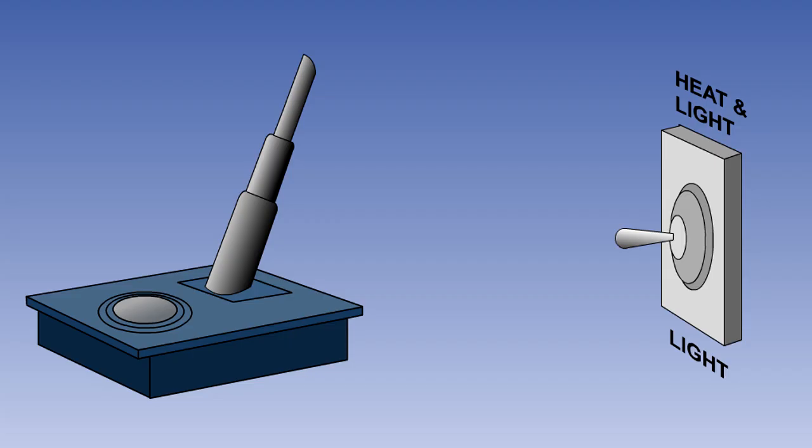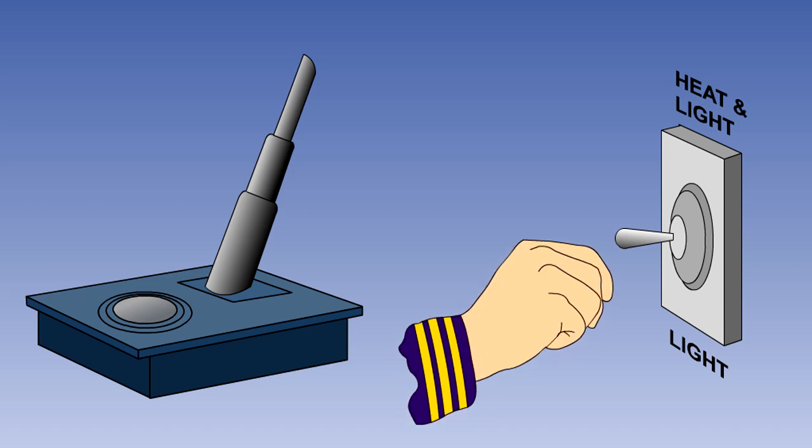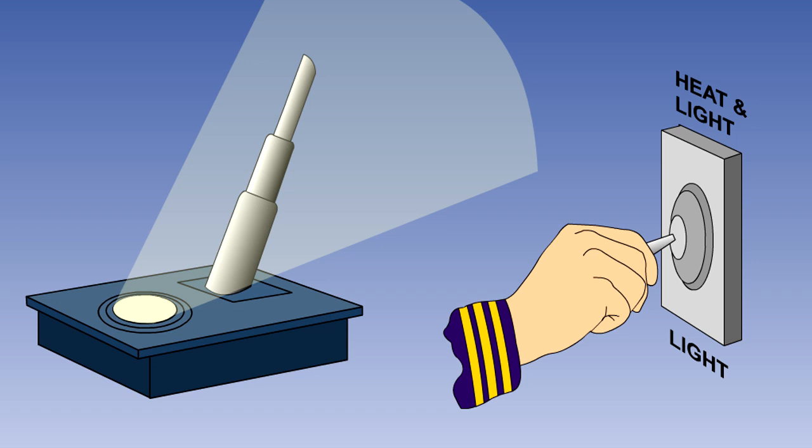To assist the pilot, some aircraft have a device known as the Teddington ice detector. This detector consists of an aerofoil-shaped mast protruding into the airflow, which is visible from the cockpit. The mast incorporates a heater element and a light to illuminate the mast at night.